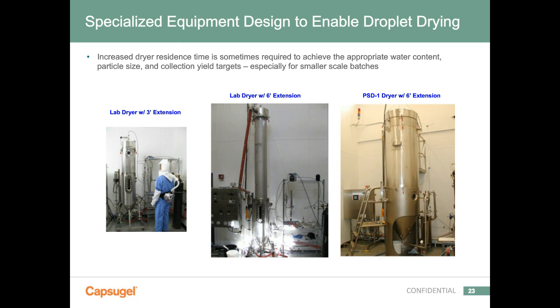So we've designed in-house some extensions of these spray dryers, either on our lab scale or on what is known as a PSD1, a large-scale manufacturer. Again, it just gives the ability for the particle itself to dry longer, which leads to better particle collection and overall morphology. And really, it's going to be specific to the product itself as well and the excipients that are included.